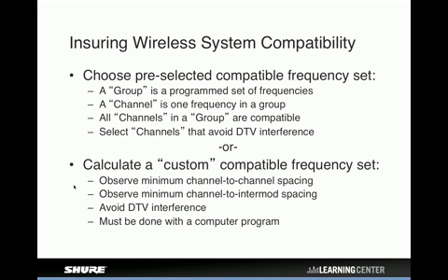That's a point I like to make: when you use software to calculate frequencies, it doesn't get rid of or eliminate intermods. They're always there, but a calculated compatible set of frequencies avoids landing on intermods that would interfere with your system. That's a very important distinction there. And again, you always want to make sure you're avoiding outside interference.